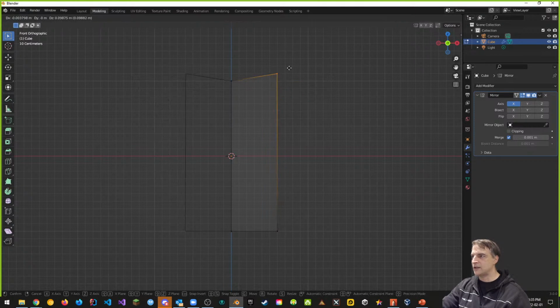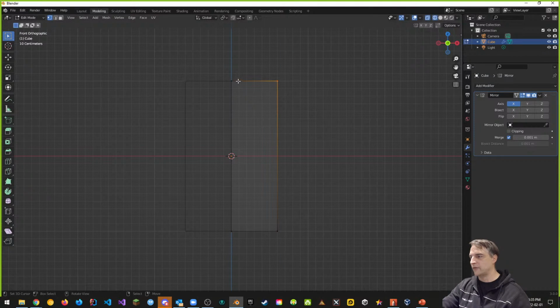If you press the G key, you notice you can do this, but if I constrain it across the Z axis, I press the Z key right after. So now you can see that I've got Z control. It kind of constrains it across the Z axis. Let me do that again. G key followed by Z, you can pull this down, right? And that's only one side of it, but I want to pull not just those sides, but also the middle.